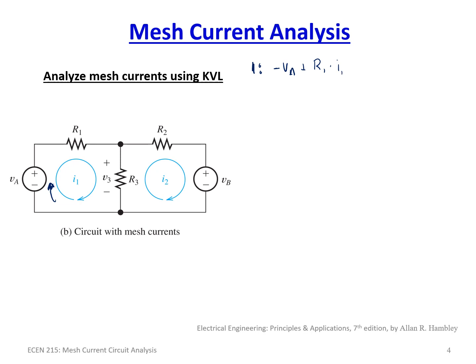That's the voltage drop across here. Ohm's law says voltage is equal to resistance times current. Now we're going to go across R3, and we're going to get this voltage V3. So we could put in V3 here, and that all must equal 0.